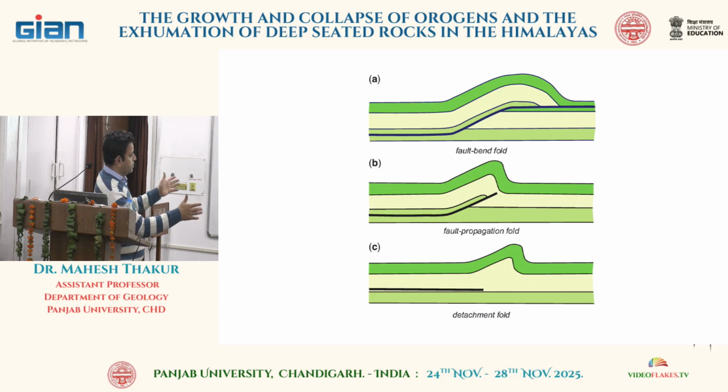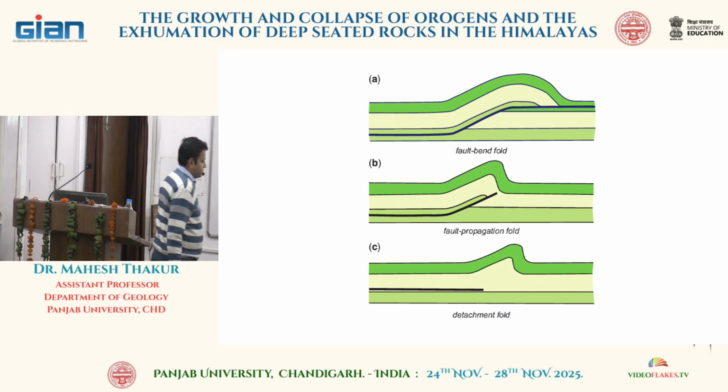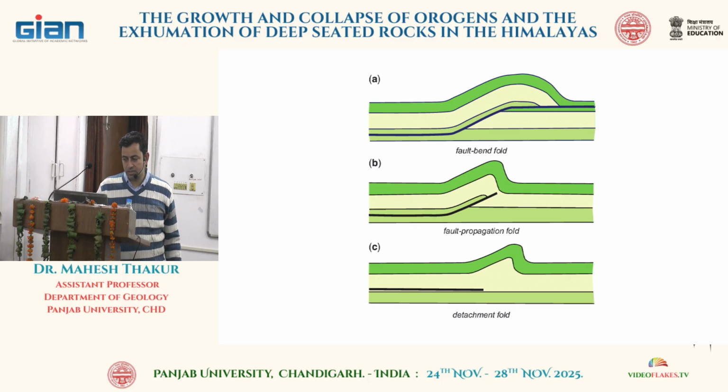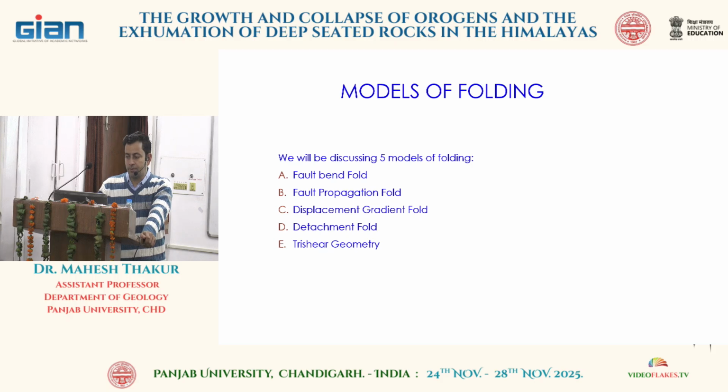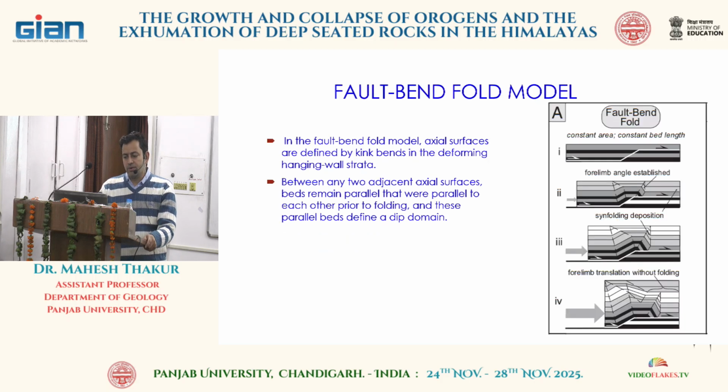You can have the compression. So in this case, the fault is not coming up to the surface. In this case, the fault is somewhere down. So the fold is actually an expression maybe of a fault. You know, beneath Chandigarh also there is a fault which we call as Piedmont fault. Maybe we can have some expression of that Piedmont fault in the southern side of the HFT. At some places we see the Piedmont fault, but in this region we have not seen any expression of that so far. So these are different types of fault and fold models.